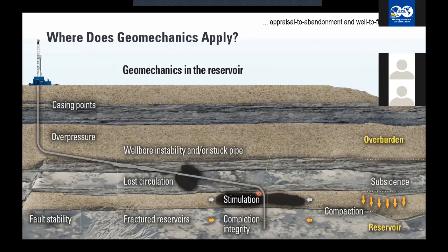You have to do a hydraulic fracturing operation, right? Because the formation permeability and porosity are quite low, you want to induce secondary porosity by creating new fractures in the formation. And for that purpose, you want to do stimulation operations, right? You want to perforate and pump a fluid into the formation so as to induce secondary porosity.